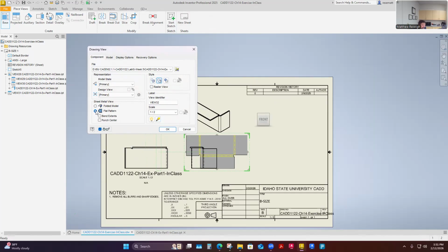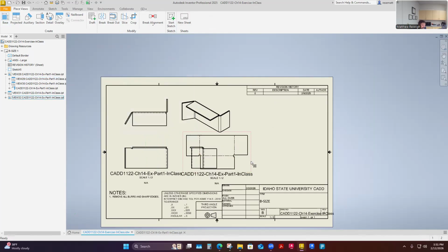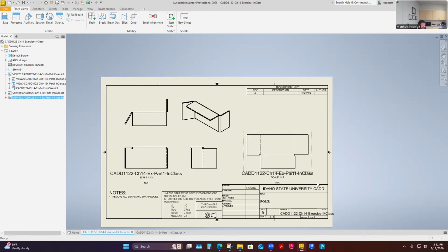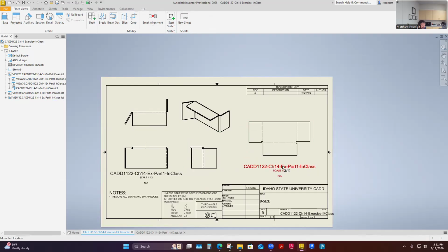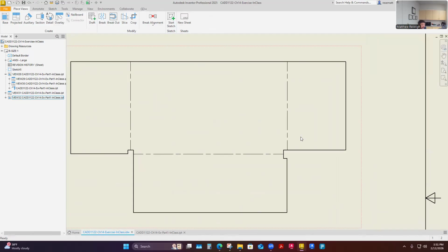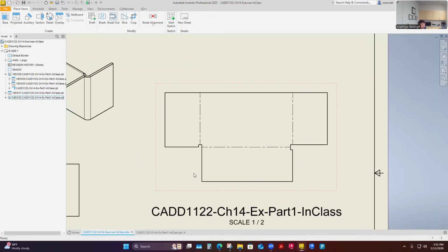And I've selected flat pattern, and I'm going to say OK. And he shows that he pulls different views of the flat patterns, but in actuality, a flat pattern like this is just going to be for machine interpreting, machine to cut. Our laser would cut this too. If I just sent this file over to it, it would cut it out with that profile out of whatever thickness I put on the machine.